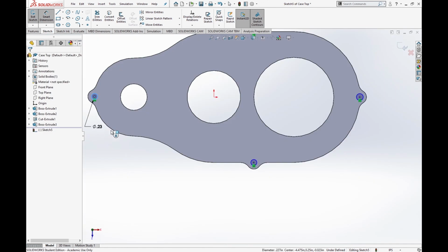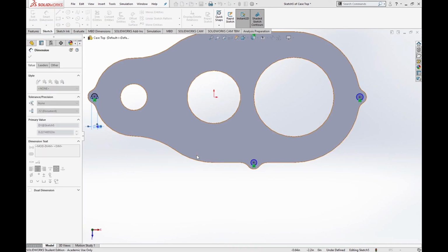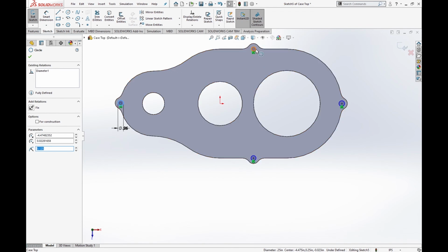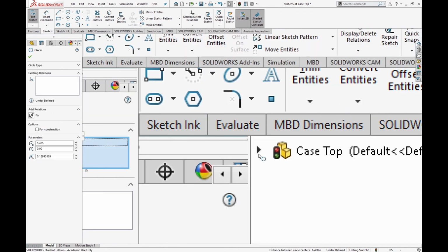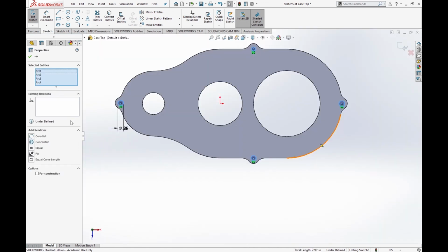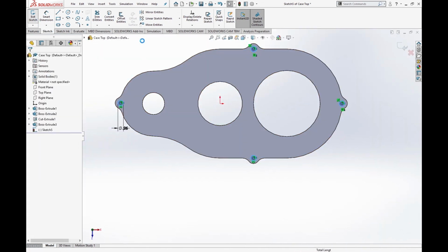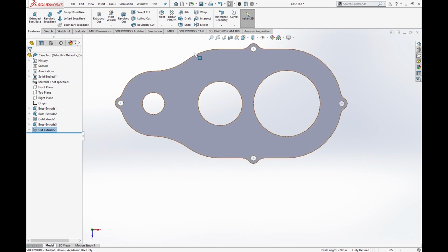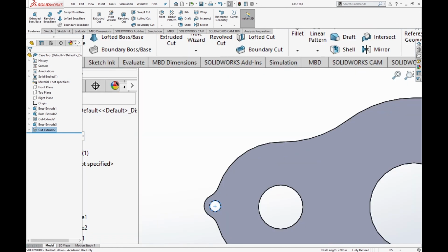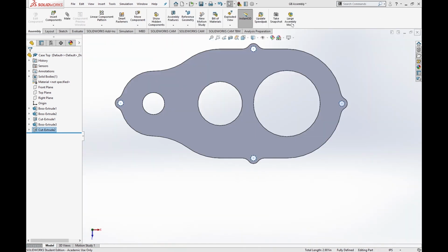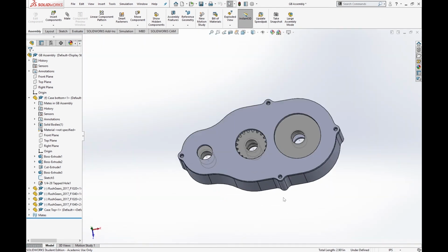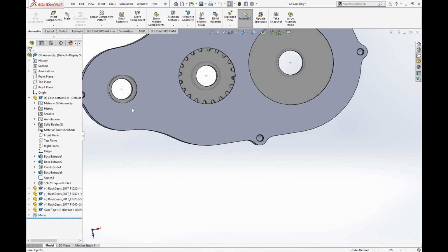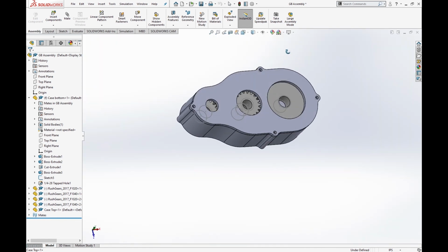Alright, so we're going to make this 0.25. You find out what the through hole size is for your 1/4-20s. I'm just trying to go fast through this tutorial so I don't bore you. We're going to make all these equal. Boom. Here's the sketch. Through all. Check mark. Boom. Save. Let's exit this one. Yes. And so now you have your tapped hole underneath. Man, I think it might be quarter inch. And yeah, and so that's that.